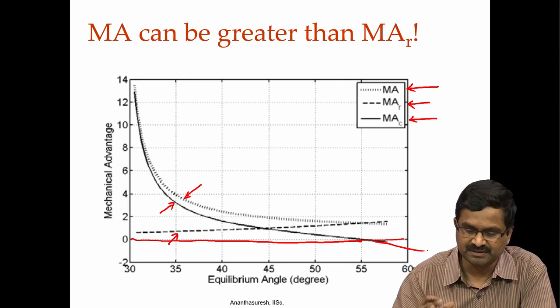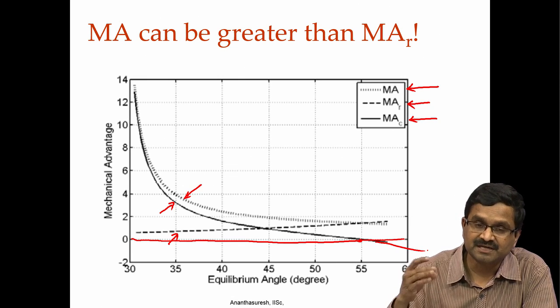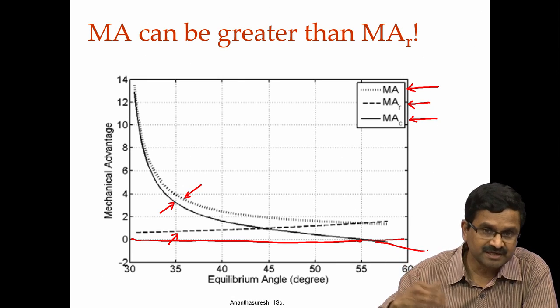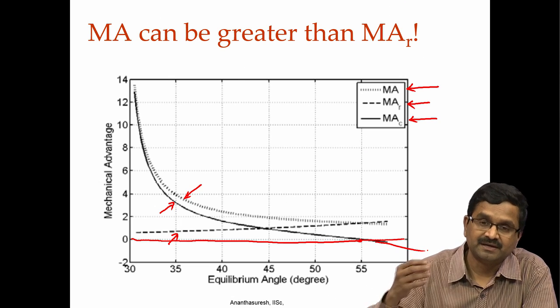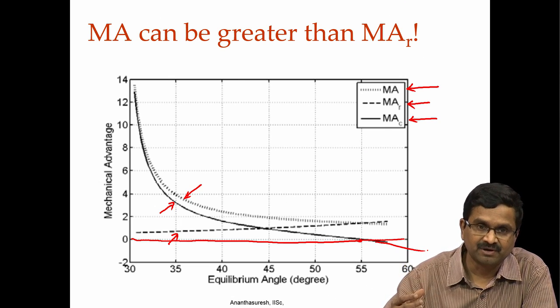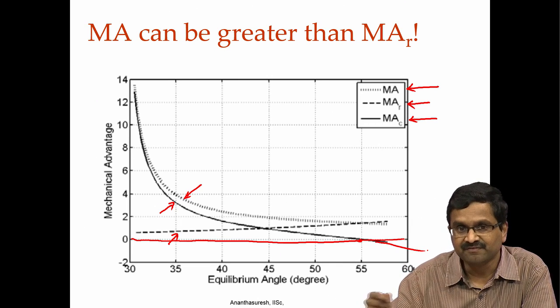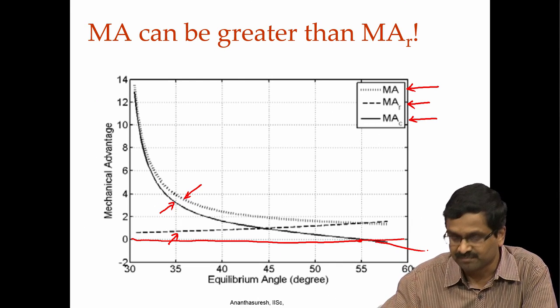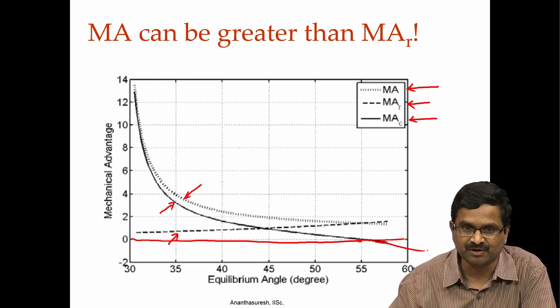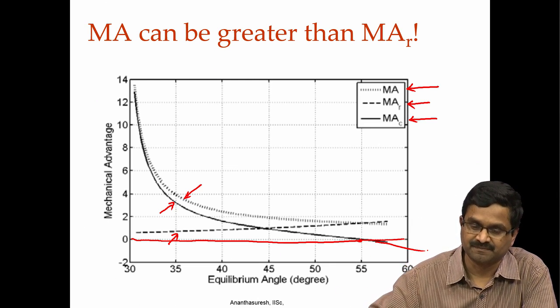Okay. That is the point here, that we need to have the delta strain energy be negative. Strain energy cannot be negative, but delta strain energy can be negative, or the rate of change of strain energy with respect to the state variable of the device, that is one particular variable, a degree of freedom you can call it, should be decreasing. Okay.